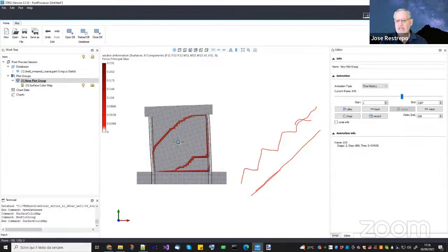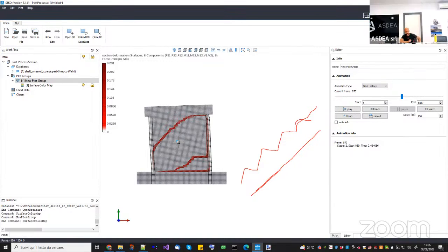But as you say, this is a challenging exercise. So it is an exercise that is going to really exercise any of the modeling techniques. As soon as the transverse reinforcement increases, say by 50% or more, it becomes easier to predict, even if it's going to fail in shear. I didn't think about playing with the amount of reinforcement. Yeah, I could have done it.